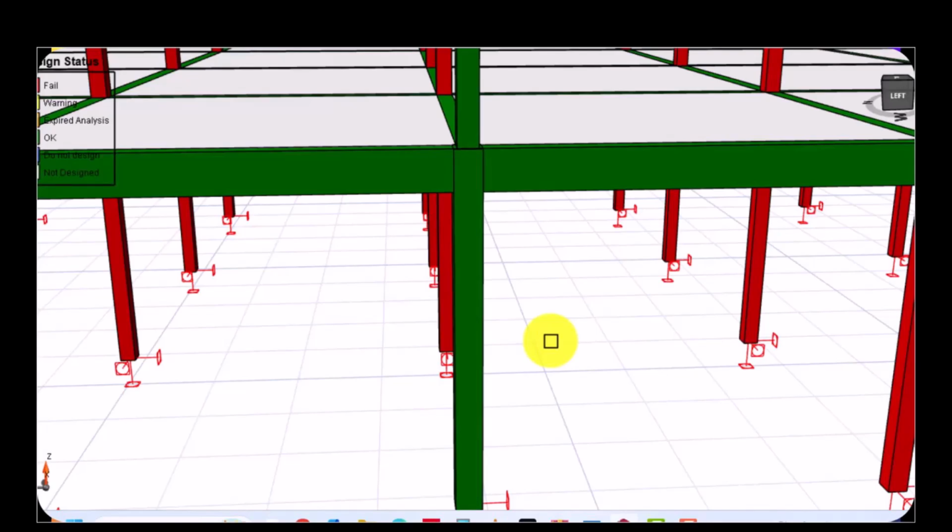It's very bad when it comes to tension. That's why we have reinforcements and links, stirrups, to restrain this expansion. That restraint we are talking about is what we call confinement.